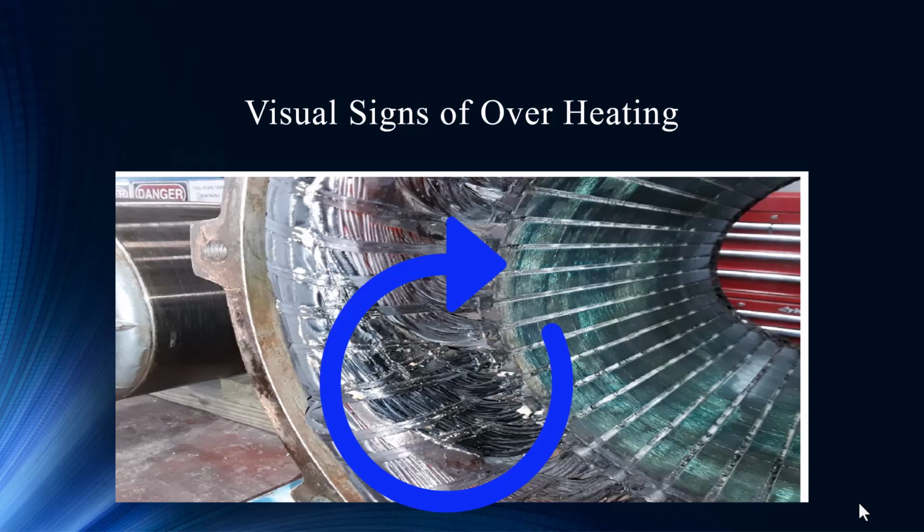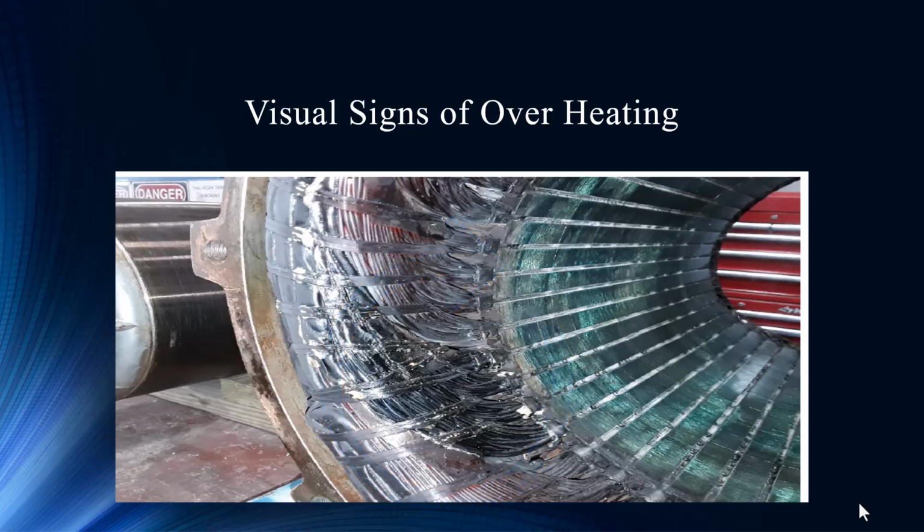And that's because it's all happening at the end turns where it's not actually on the core. Yeah. You know, there's laminations. There's a thermal or insulating paper that is keeping it from ground. Yet. Exactly. But you're looking at this motor, the life expectancy is very, very short.